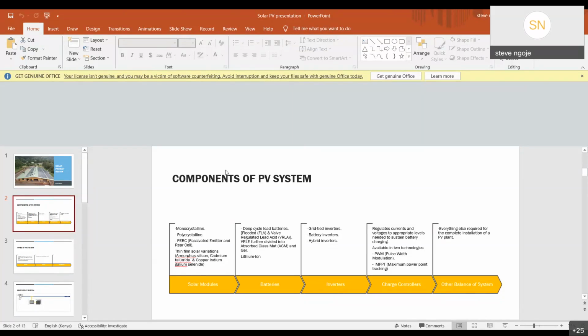First, if you connect the panel to the charge controller, it forces the voltage to come lower, so that if, for example, the battery has been discharged, the voltage of the battery most of the time reduces slightly. So when it charges, the module voltage must be brought lower so that as the battery charges and increases in charge, the charge controller will let in more voltage from the panel.